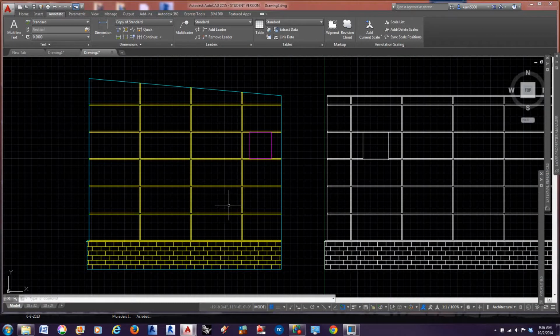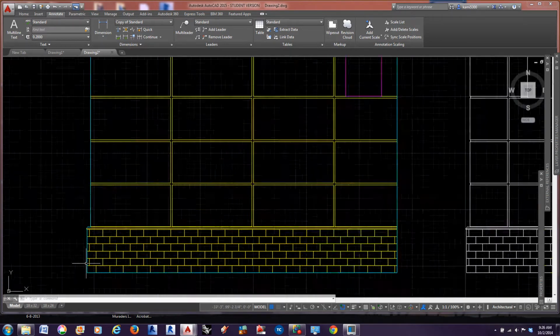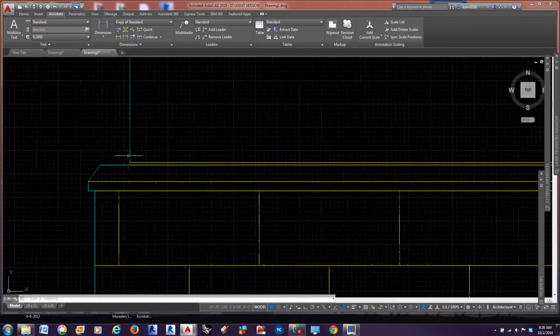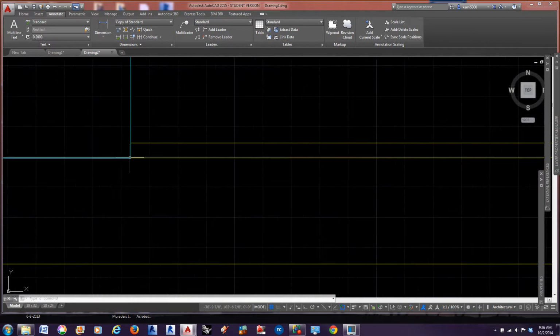Okay, so I'm just going to add a little bit more to this video. To make this a little bit cleaner, once you have these lines set the way you want, we can actually completely join the exterior perimeter lines together so that it cuts all in one line and doesn't start and stop.